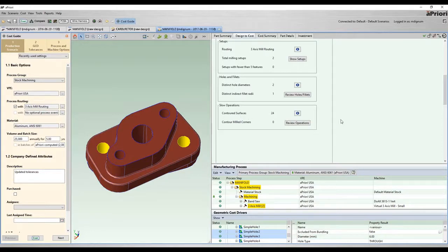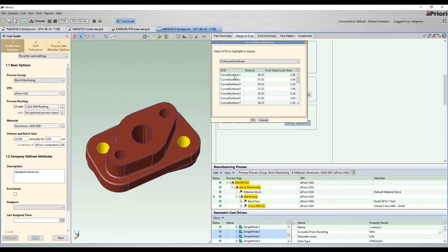And then the last panel that we have here is just exposing slow, expensive machining operations. So contouring is a very slow, very expensive machining operation that should only really be used when absolutely necessary. If you have a specific shape that's required to meet the functionality of your part, then that requires contouring. That is understandable, but whenever possible, it should be avoided.